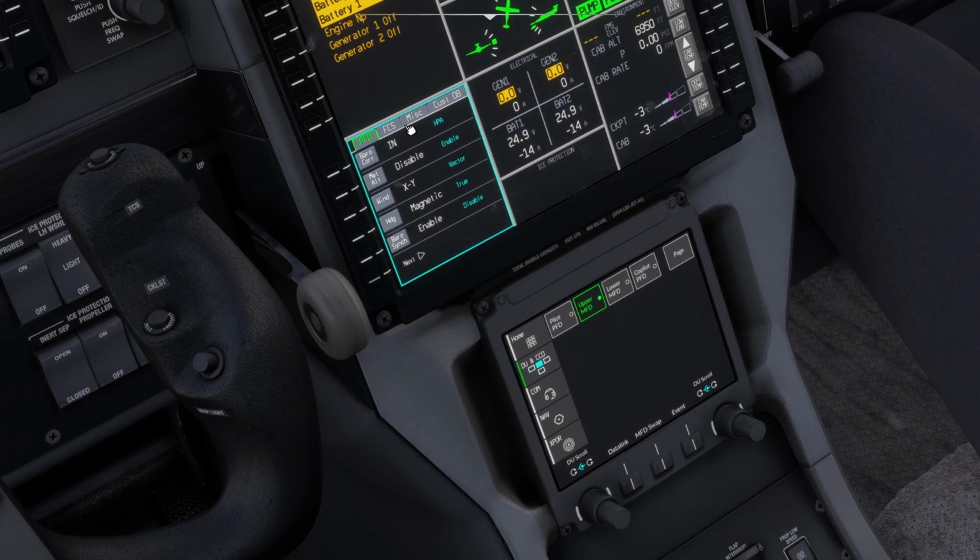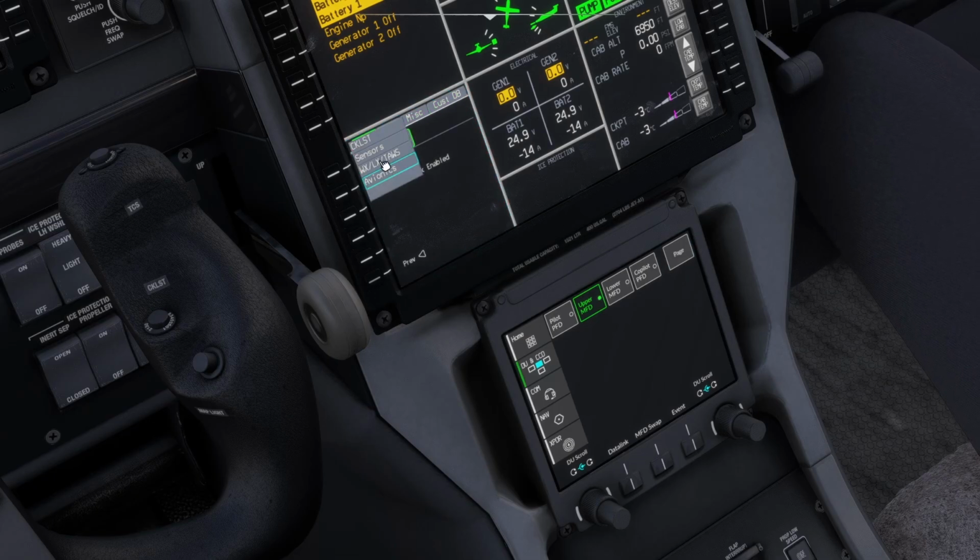So on the PFD, you can change the settings by using this screen. You can see the version which is enabled. You can go to the FCS, enable certain things, right? The steep approach, enable the thrust director. You can go to miscellaneous where you can activate the keyboard pop-up and the custom DB. So those are the things which you can change by using that button.